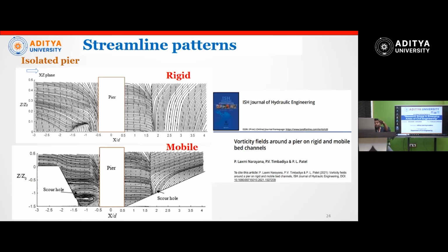With this visualization we can know where exactly the stagnation point is, where the boundary layer has separated. We can see the boundary layer separated at around 1.5 to 2. There I can see the separation. So these are some fundamentals that help us understand the actual flow physics.